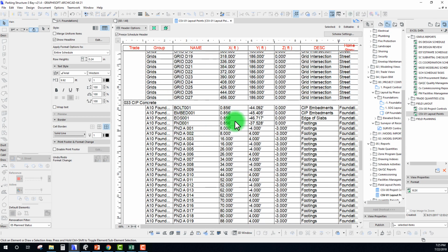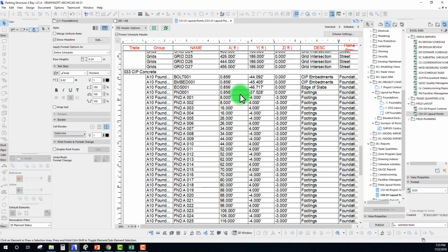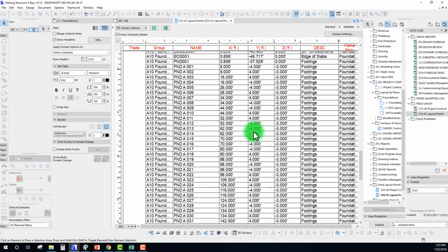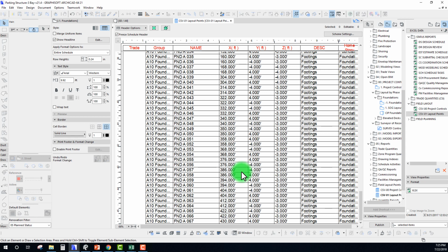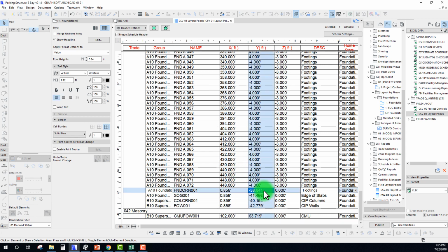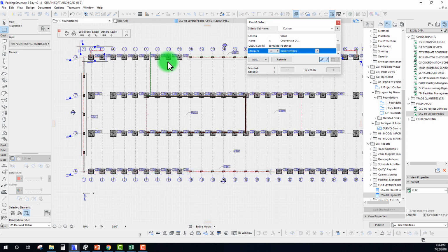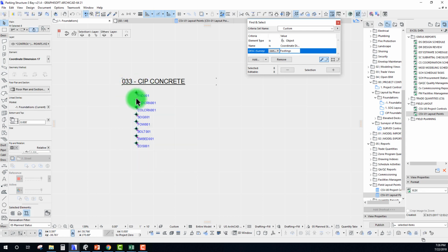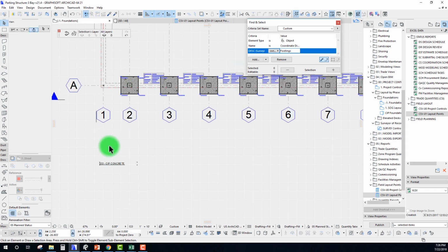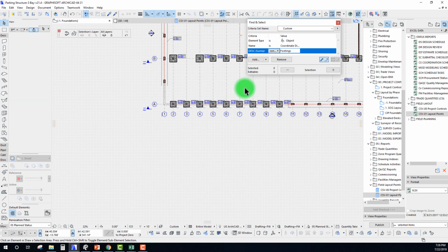And okay, so we have all these values in here. Because those footings were all centered on grid, we can see real quickly that everything has a 0.000. If I scanned right over that really quickly, and I did have anything that was slightly off, we'd actually see that coming through in those numbers. Like this particular one, that 841, that jumps out to me, but I bet if I go and look at that, that's probably one of these originals, or sorry, one of the examples that I brought in. So we can actually go ahead and delete all of these.